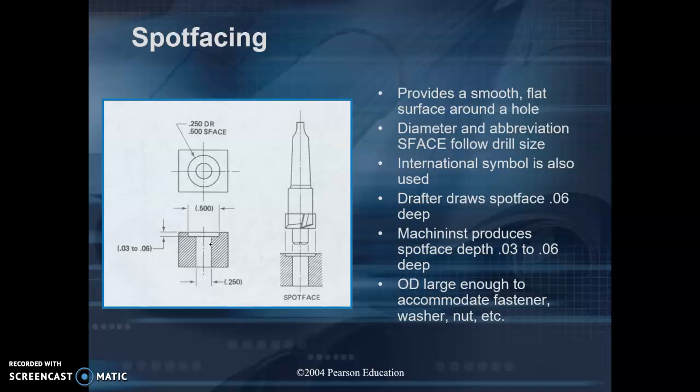Oftentimes, it is drilled, and after it is drilled with a drill bit, you come back with a specialized tool that sits down into that hole, and then these splines remove material from the surface of that hole, leaving what is essentially a very shallow counterbore.